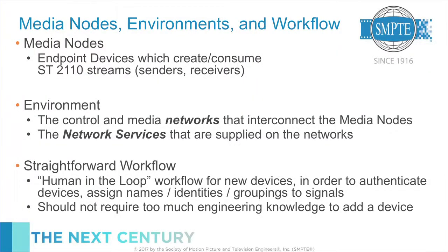What's a media node? Well, I had to come up with some word other than device, because device means a different thing to every person who hears it. So okay, well, let's call these things media nodes, because that's as good as any. It exposes an IS-04 node API. So media nodes are things that speak and eat 2110. The environment has control networks and media networks that interact with these nodes.